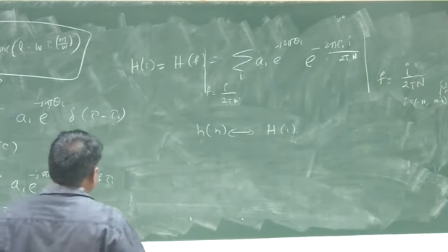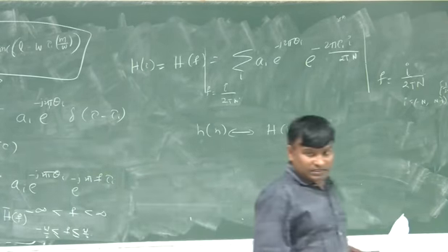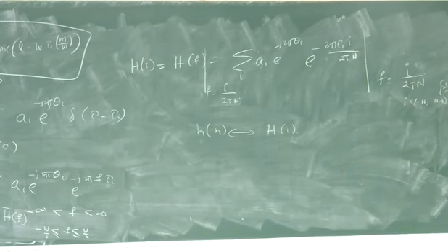That is nothing but the impulse response in time domain, of course, truncated to N taps. So it is time limited to N taps. As capital N becomes larger and larger, you get a better representation. So this is one way of observing the time domain impulse response using FFT.